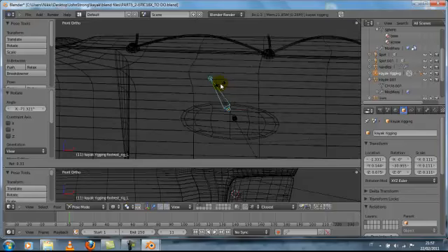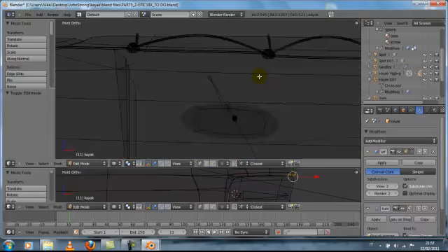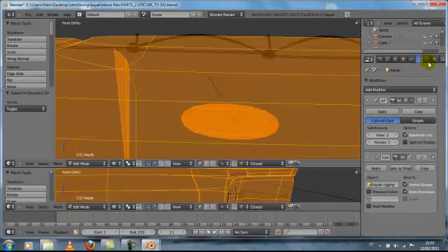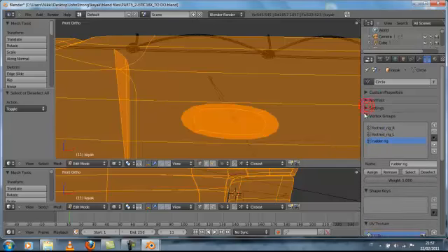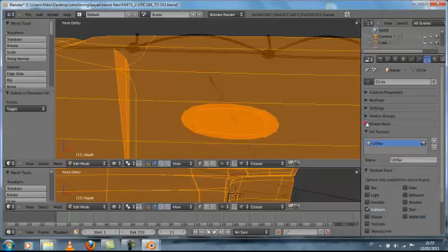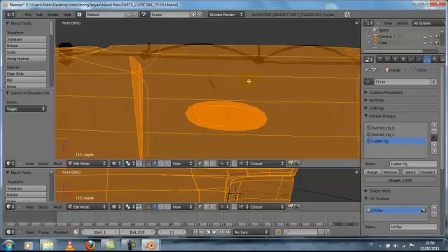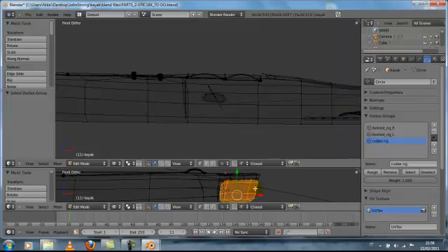So now what I do is select the mesh, go in edit mode, and here in vertex groups there are the vertex groups we have created when we made the parent between the mesh and the rigging. Let's see, when I select the rudder, it is just the rudder.